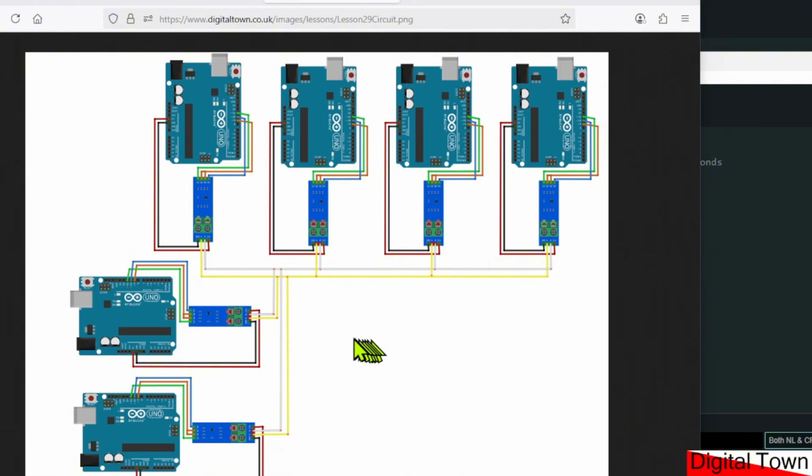Now there is one scenario that cannot be allowed to happen, and that is we cannot have multiple transmissions running at the same time, because we've got a two-wire system here. So if this Arduino starts sending out a load of signals and this Arduino starts sending out a load of signals, they are either going to cancel each other out or completely confuse each other.